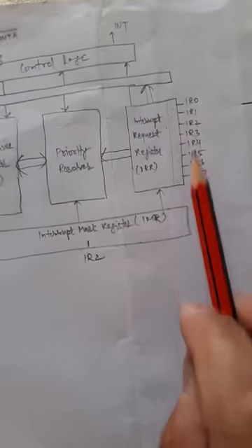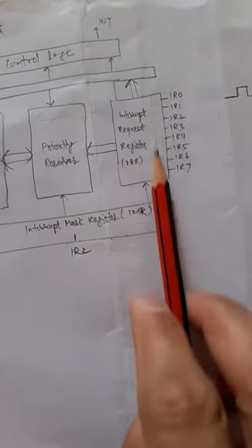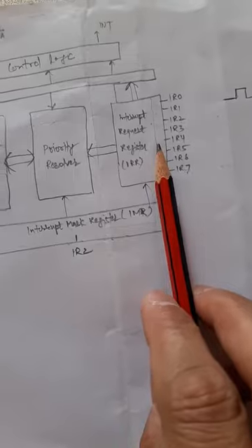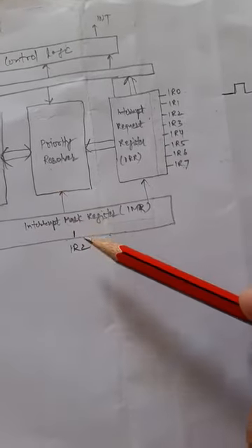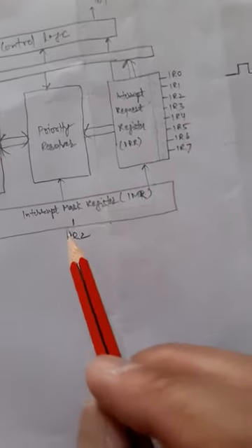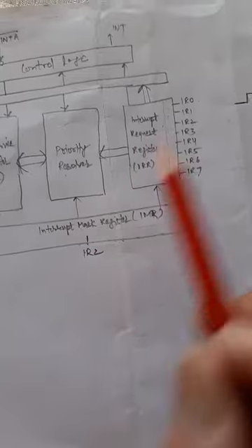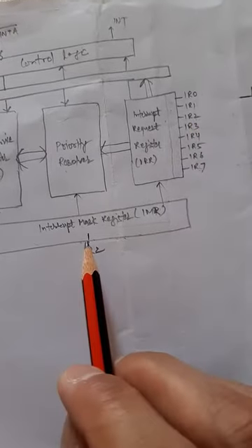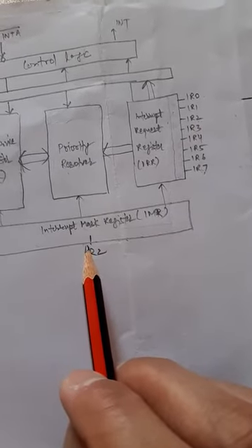First, interrupt 2 and interrupt 7 have occurred, so the corresponding bits become 1. Now the priority resolver checks the interrupt mask register. IR2 is masked. IR2 is of higher priority than IR5, but since it is masked, this interrupt will immediately be discarded, because the MPU is not interested in taking this interrupt at this time. So IR2 is discarded.